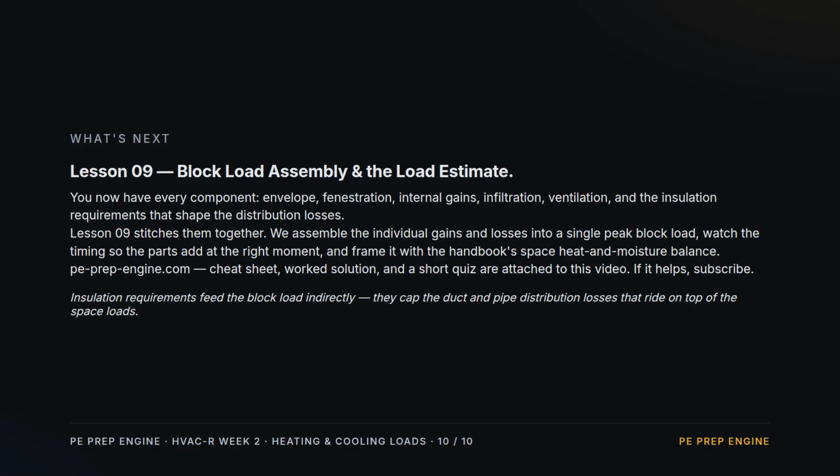Next, Lesson 9, Block Load Assembly and the Load Estimate. You now have every component: envelope, fenestration, internal gains, infiltration, ventilation, and today's insulation requirements. We stitch them into a single peak block load, mind the timing so the parts add at the right moment, and frame it with the Handbook space, heat, and moisture balance.